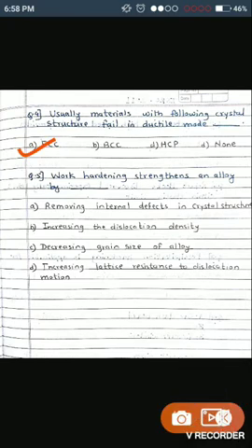Now the explanation for this question can be based on the movement of slip planes. In the case of FCC, slip plane movement is easy, that's why they fail more by ductile failure. In the case of BCC, at lower temperature, the movement of slip planes, the dislocation movement, is less.